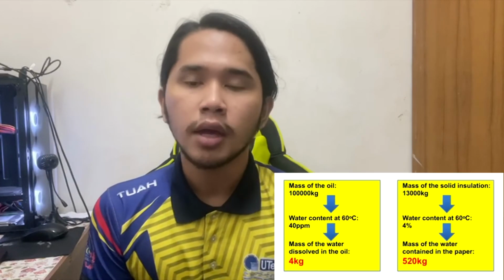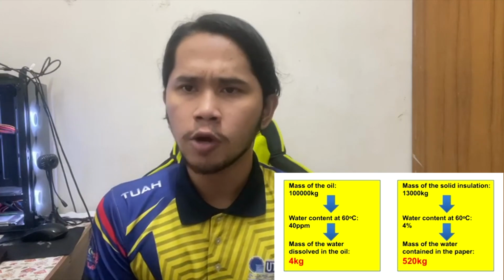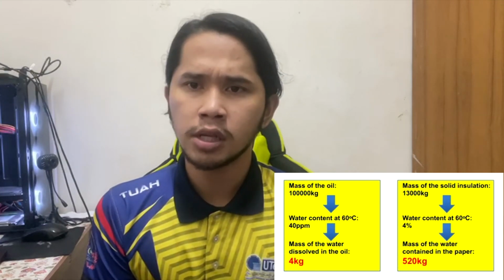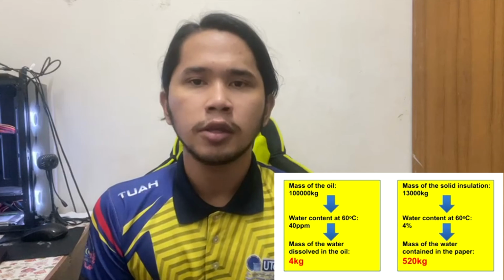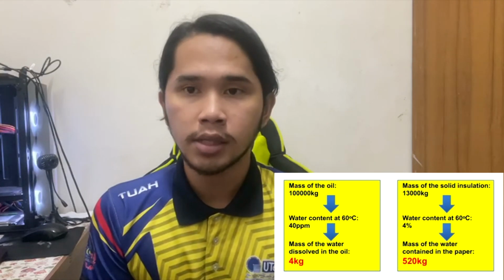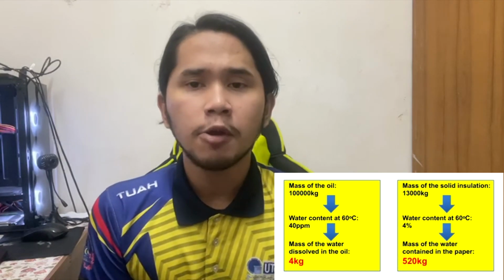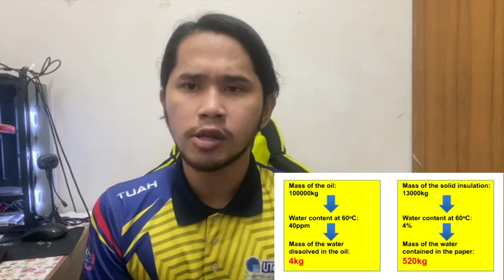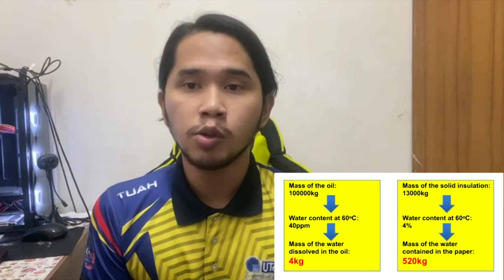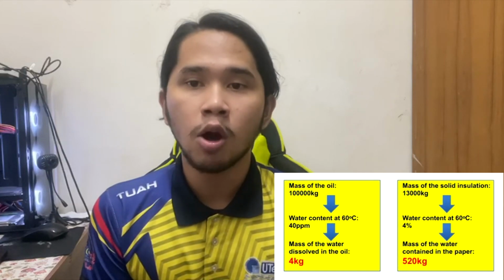And how to measure water in paper insulation? There is no practical direct way of measuring moisture levels in transformer insulation. Therefore, a wet condition may go unnoticed for a long time. This has led to an indirect method of moisture estimation. The direct method takes paper samples from the transformer and tests for moisture content using KFT. Limited use since possible only during repair or teardown.